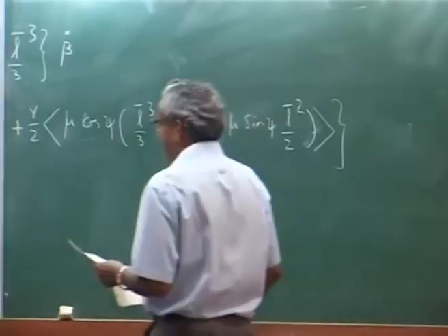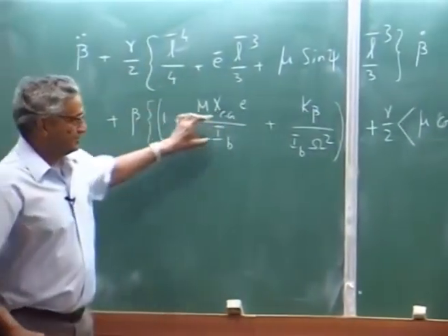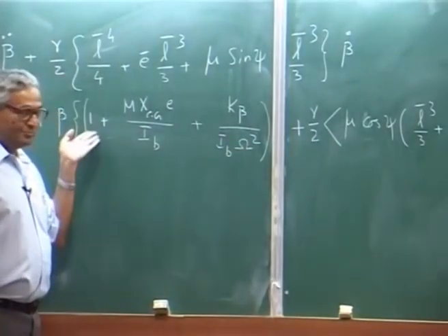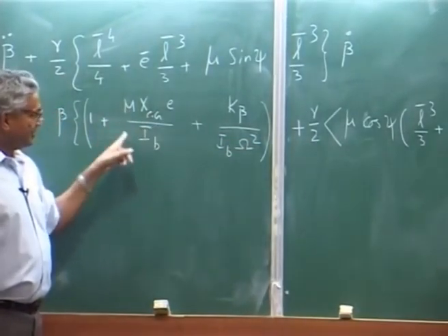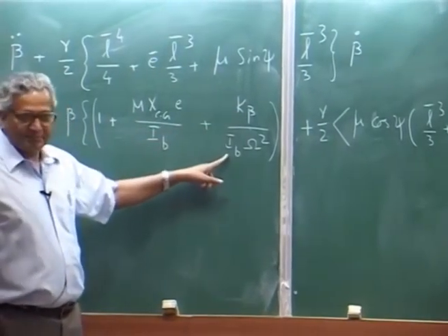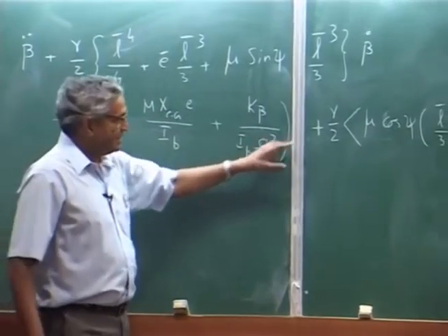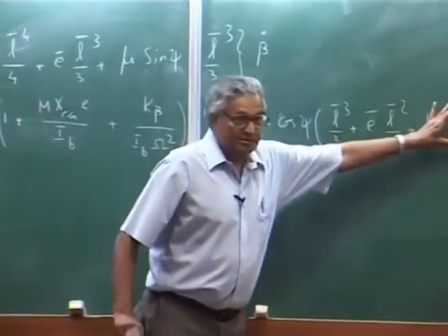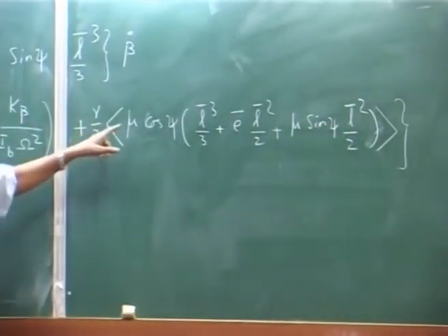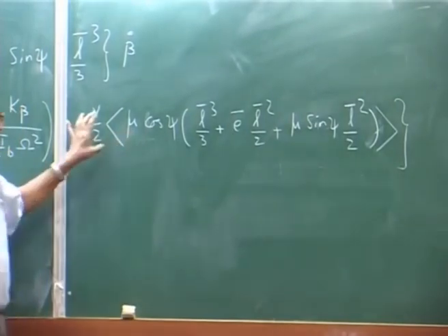Okay. This is my stiffness term, please understand. I have 1 plus this, I will explain to you what this term is: root spring divided by blade mass moment of inertia non-dimensional omega square. This is due to the aerodynamics gamma, and this is time varying. This is only with respect to mu, forward speed. If forward speed is 0, this term is 0.